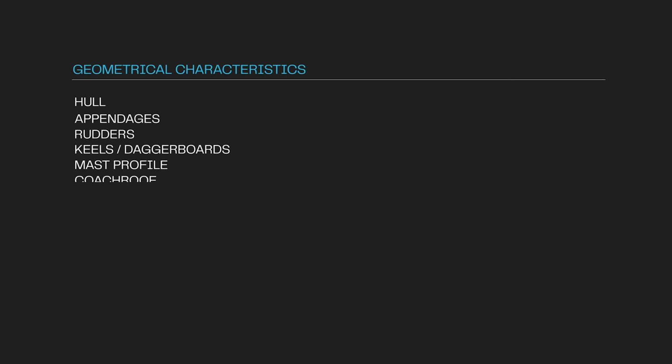Yeah. And a couple of things to further complicate that: the VPP is producing an estimate of your performance in these conditions, but it has to make a lot of assumptions. Besides the assumptions we made inputting the data, describing the hull shape and the sail plan and all these things, it also assumes a bunch of other things that are largely unobtainable. It assumes that your bottom condition is X, that your sails are perfect, that your use of the sails is perfect, and all of these things are perfect. Your skipper is perfect.